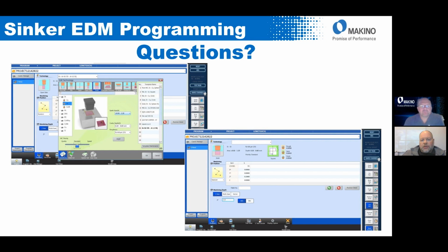Because you're going in small and it's getting larger with that draft as it goes up, we then use that draft angle to remove some of that extra stock at the top, because it's larger than the bottom. We do that by going more aggressive on the processing. So we basically cheat back processes to be more aggressive and get a higher removal rate.